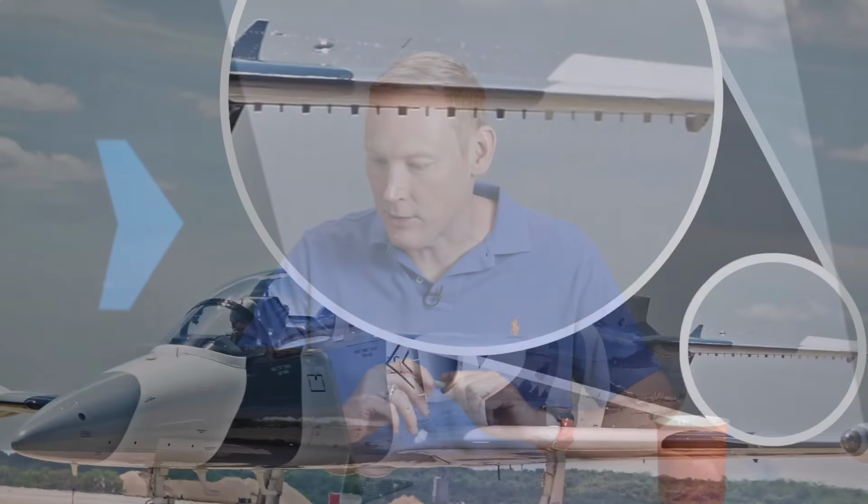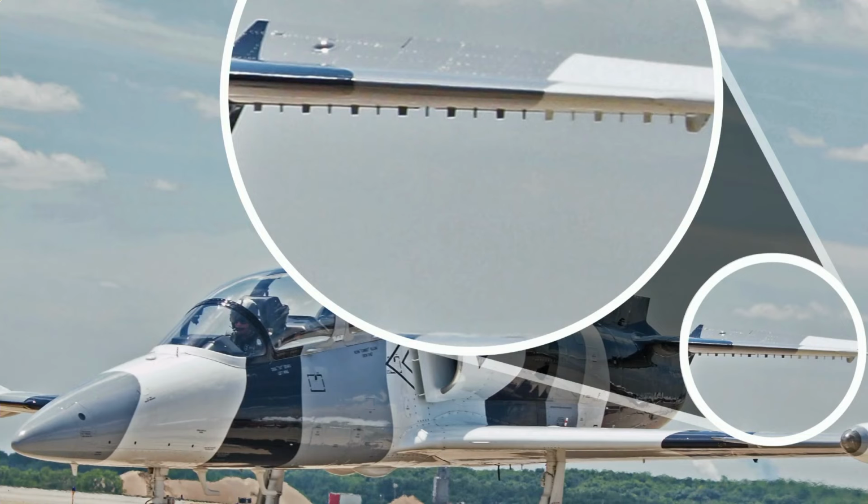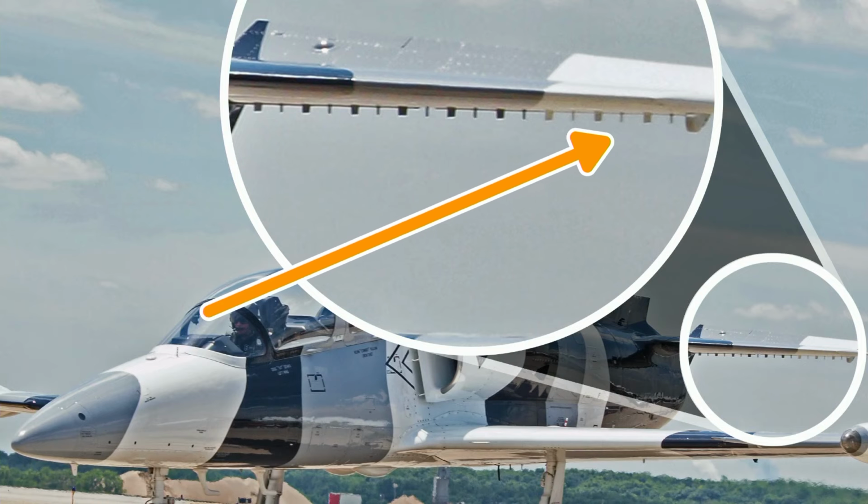So let's take a look at this L-39 Albatross, which is a subsonic airplane. But what you can see here are all of these vortex generators. So vortex generators are just angled pieces of metal, but what they do is they generate a little vortex that swirls and pumps high energy air into the boundary layer.